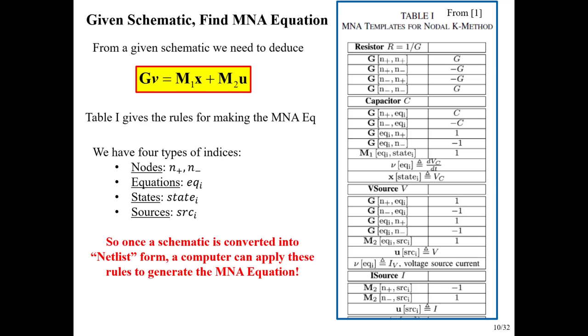It's just doing it inside. But when you run LTSpice, it might give you an error and say something, netlist, blah, blah, blah. Well, the netlist is the thing that it makes from the schematic, and then it uses the netlist to generate all of these different indices to populate its equations. We're going to do a similar kind of thing, okay?